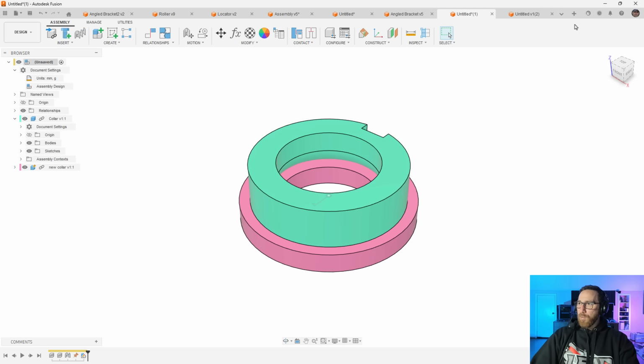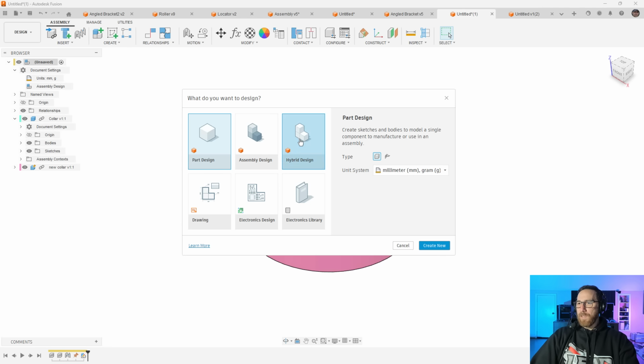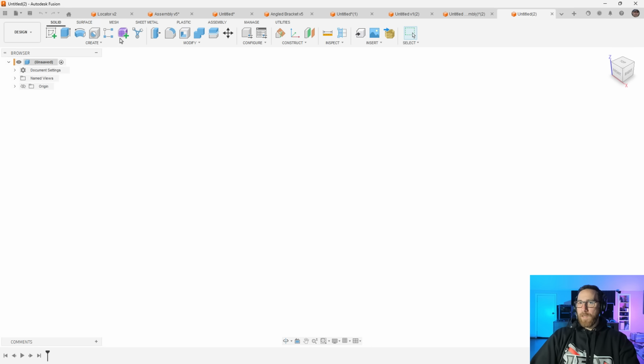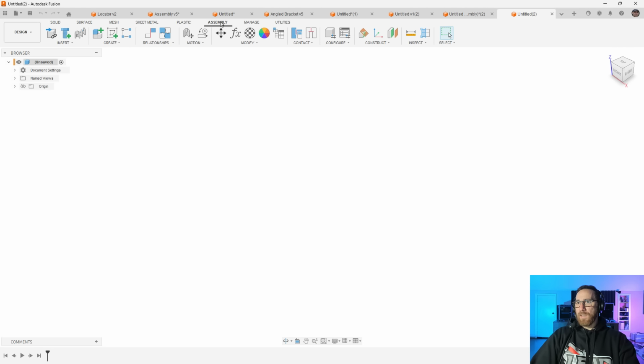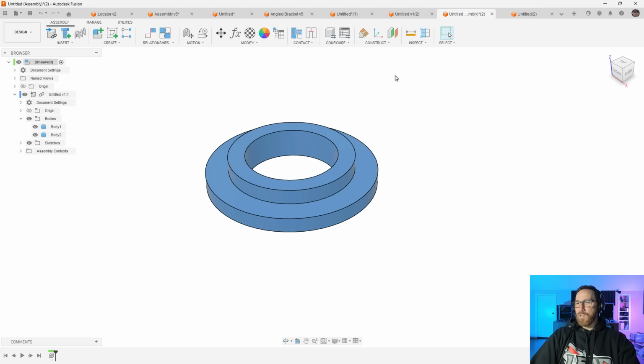And then that third approach, that hybrid approach, is really, again, what we do now. We can create multiple bodies, we can convert them to components. The main difference that you're going to see here is that the assembly tools now exist on their own. And so instead of having an assemble dropdown, you just have to go to the assembly menu. And part of the reason for that is the way that Fusion has done this is actually to just hide certain things from us.